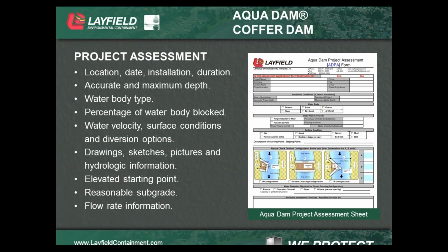We always like to get drawings, sketches, pictures worth 1,000 words, and then any kind of hydrological information that you might have relating to stream flows, those kinds of things are valuable pieces of information to enable us to evaluate each project on its own merits, as opposed to a broad brush approach that an Aqua Dam is going to work in every application. There's some scenarios where stream flows and those kinds of things are too great for an Aqua Dam, where the stream is too narrow for an Aqua Dam to do a shoreline restoration project, let's say. Just things to consider, and that's why we get the assessment form filled out.